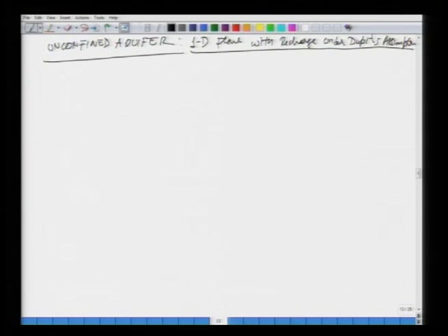This will be the most general case as far as one dimensional flow is concerned. If the recharge is not there, we can just put W equal to 0 in the resulting equations. So, we would like to derive an expression which is the most general one.